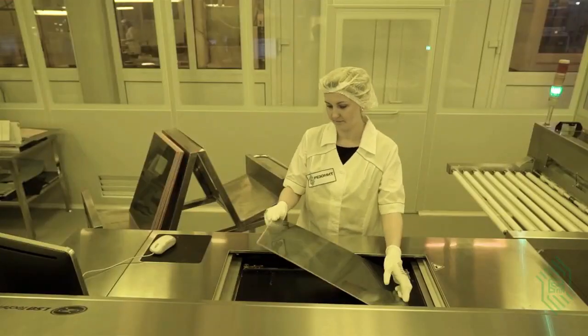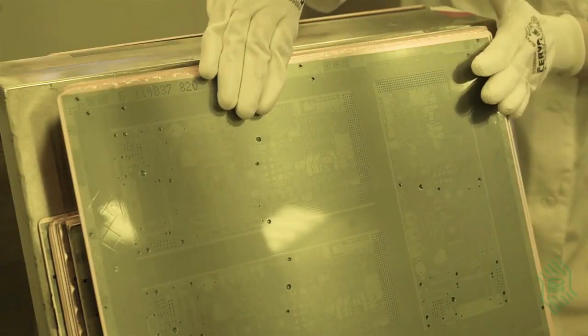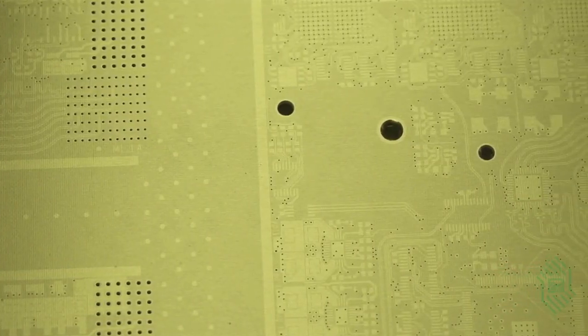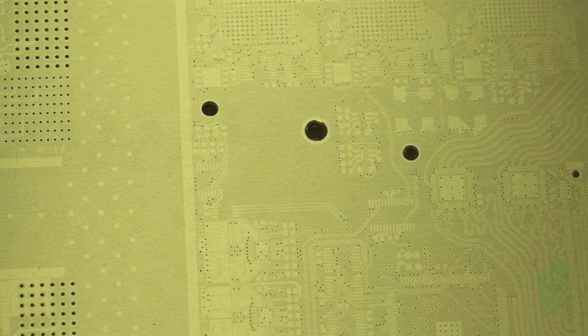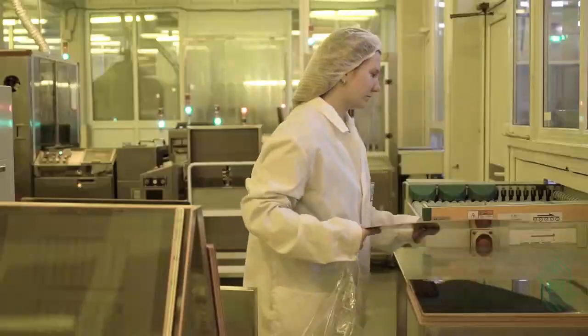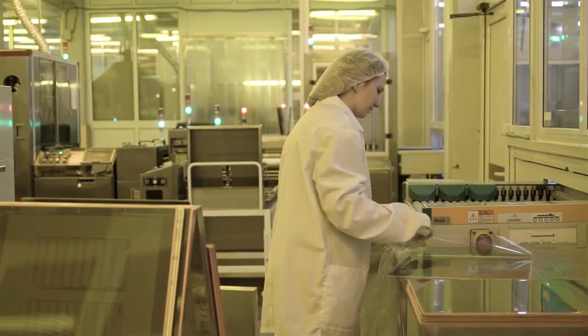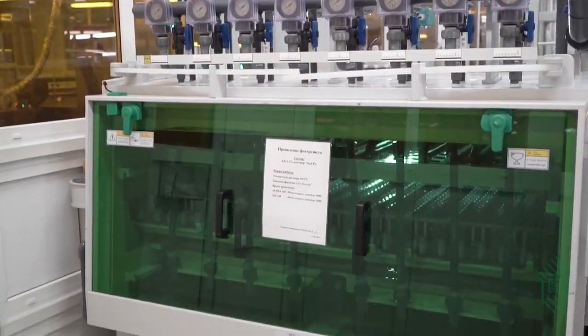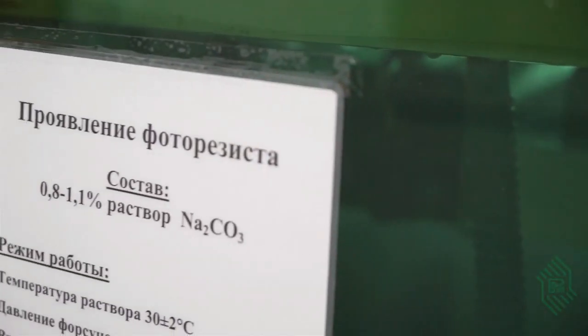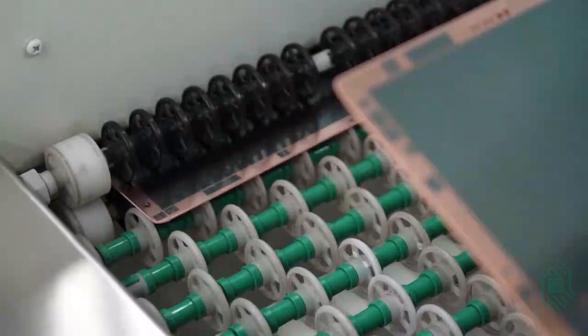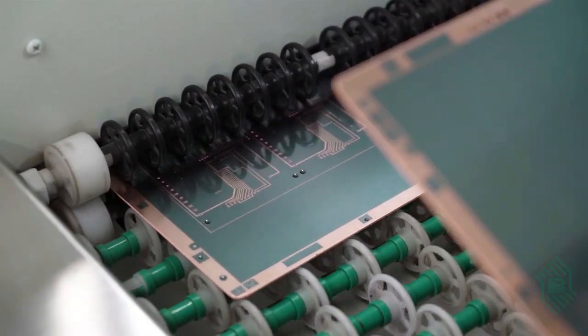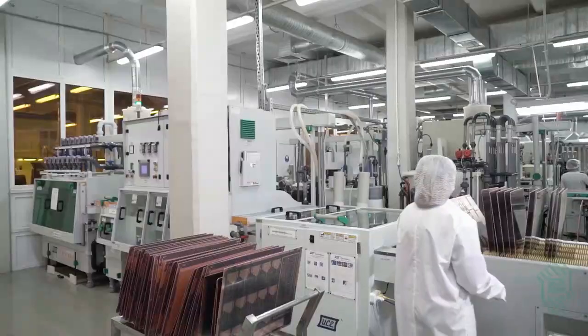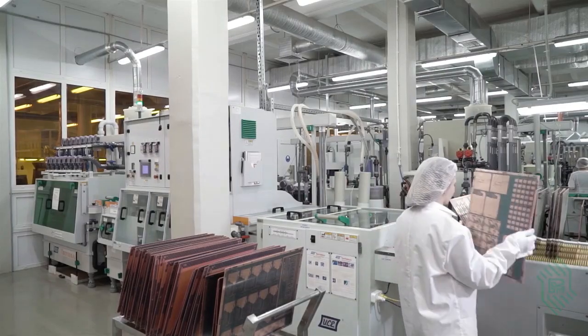The combination of automatic print alignment and high-resolution printing provides for the imaging of PCBs up to 3 mil line space. Portions of the unexposed photoresist are dissolved in the developing solution, opening the holes and the pattern to deposit the galvanic copper. After a quality control inspection, the panels are transferred to the pattern plating area.